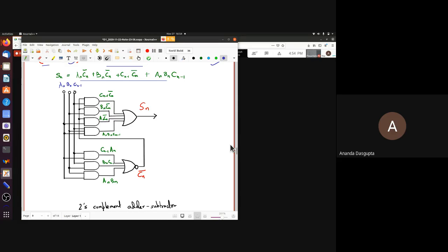However, you may have further simplifications if, for example, you use part of the output which you are using for A, one of the segments, to simplify the connection for B or the connection for C, and so on. So that is a rather complicated situation because you have 7 distinct outputs. Finding the simplest possible, that is the one which will take the least number of gates and be easiest to implement, will be rather difficult.